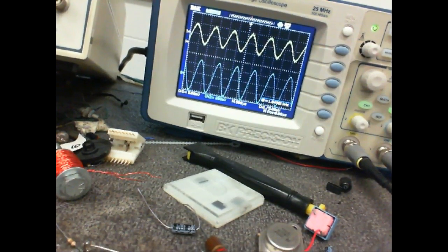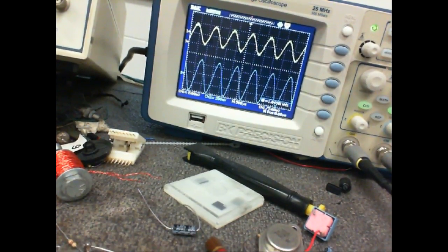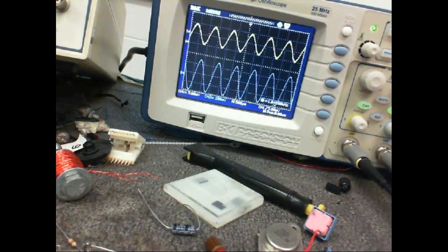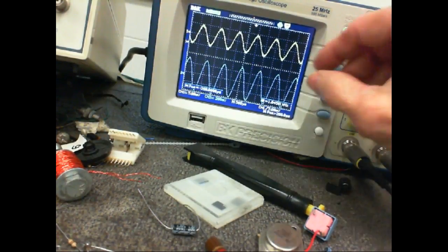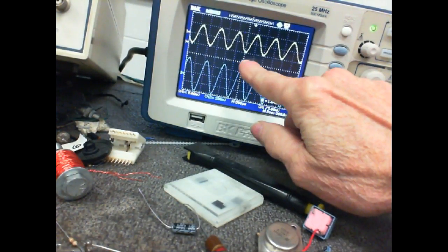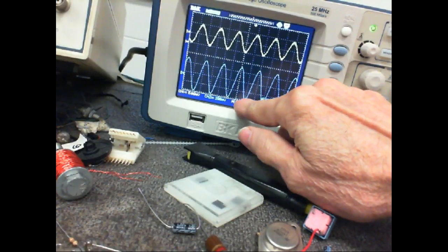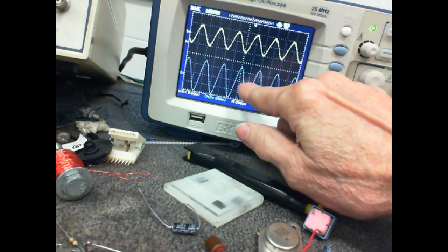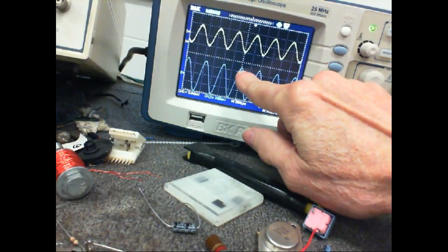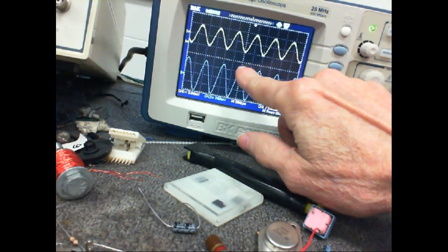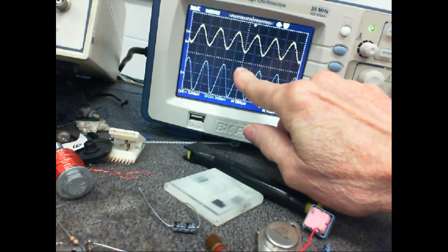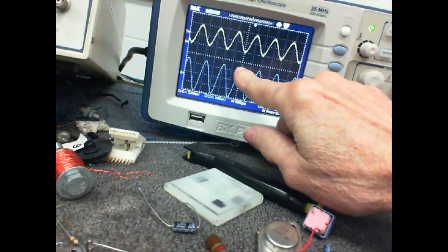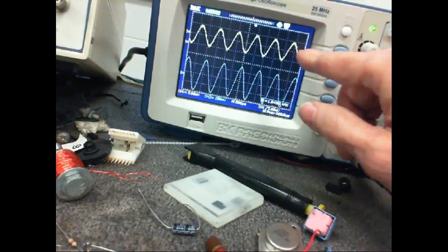Is everybody okay? Did y'all get what I get? Yes or no? Even though it got kind of confusing. All we did, we got it 2 ways. I counted, but what we're going to do is do the math. I'm counting 1, 2, 3, and each one of these is 0.2, so it's 3.6 divisions times 0.2 volts. That's 720 millivolts.